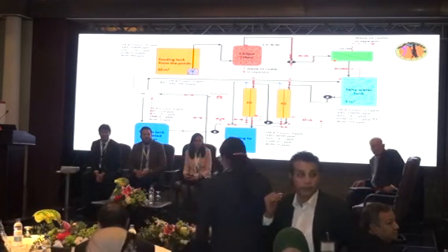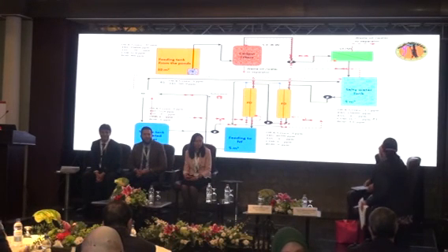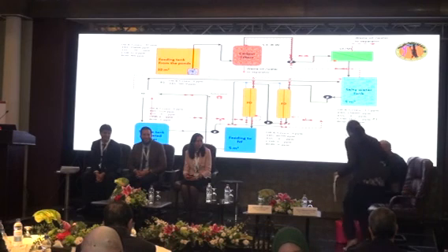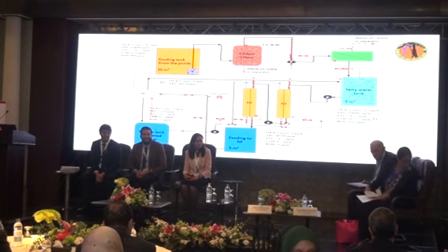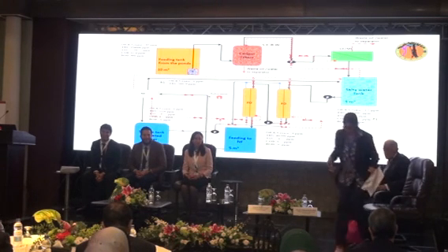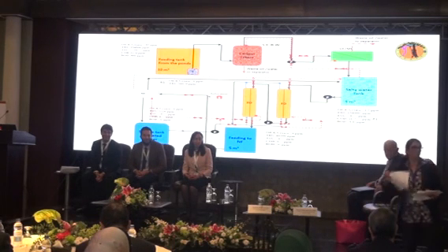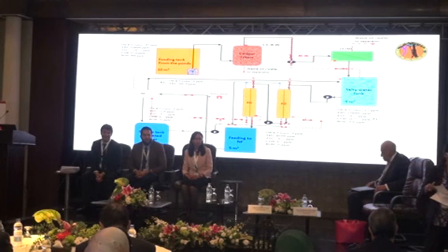My question is to Mr. Alexander and Mr. Tamer, as you are both involved with all catalysts. I am from SOBC, and I have a delayed coker to change to Uniflex or H-oil. What is the difference between the two units, and the comparison between hydrogen consumption, the catalyst cycle lifetime, and the percent of the product, and how can we shift to the severe condition to make it flexible for middle distillate or petrochemicals? Thank you.